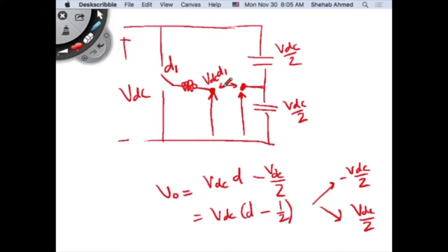So it depends on what the output voltage looks like and how you want to optimize the system, because again, you can produce the same output voltage that you want on the load. For the half bridge configuration, you save on switches, right? You only have 2 switches in the half bridge, and 2 capacitors, versus in the full bridge, you have 4 different switches, right? So you save on the switches. But for the half bridge, you would have to bump up the VDC to twice its value for the full bridge if you want to get the same output voltage on the load. Right? To receive the same output voltage on the load, the half bridge converter would need a VDC of twice the full bridge inverter.